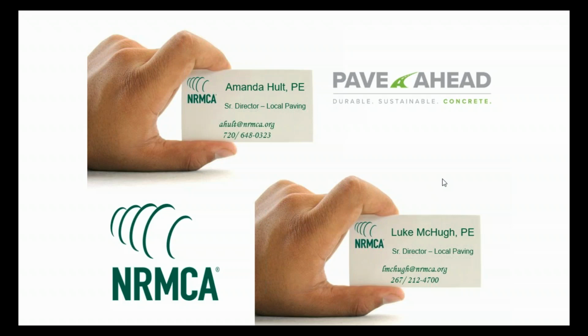Yeah, and typically what you might want to do also is decrease your joint spacing to decrease or relieve some of those warping or curling stresses that you might get from the asphalt or cement treated base. True, but there is potential for restraint on some of those types of treated materials below the concrete.